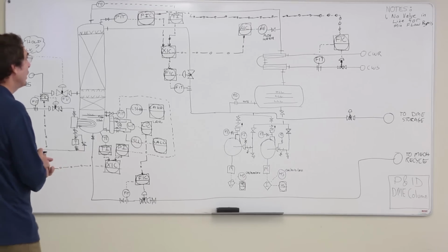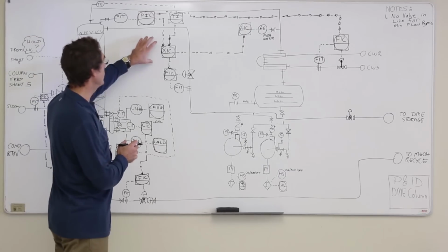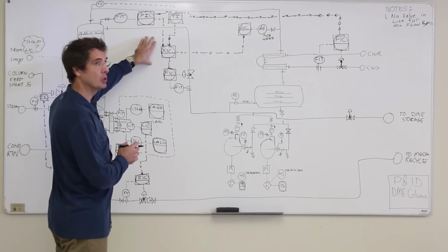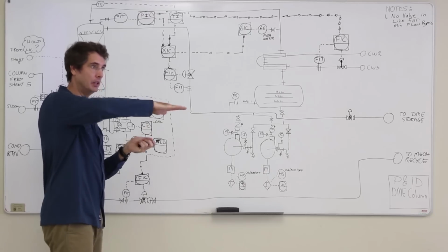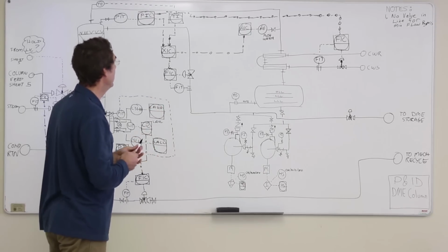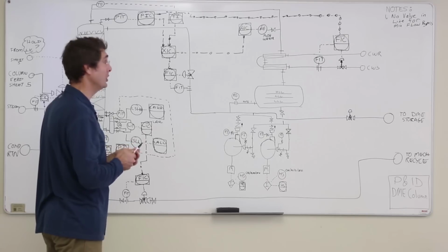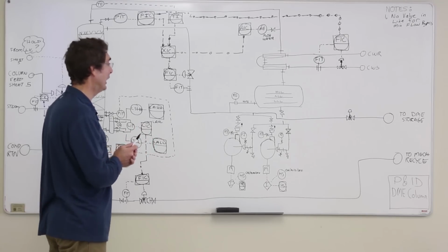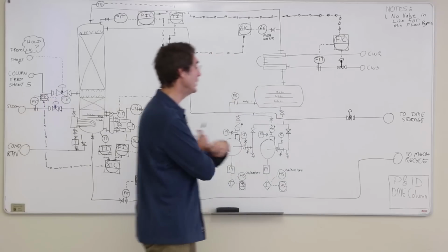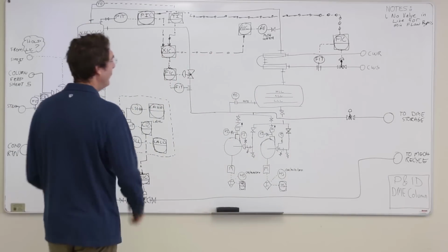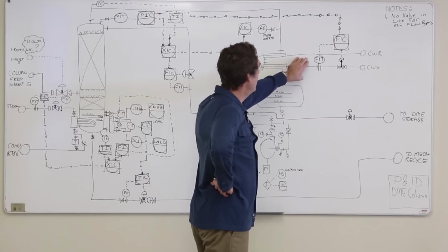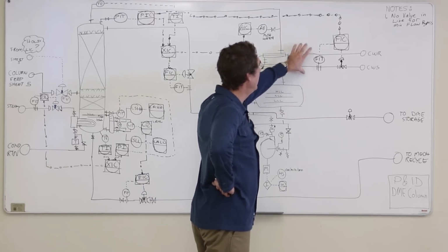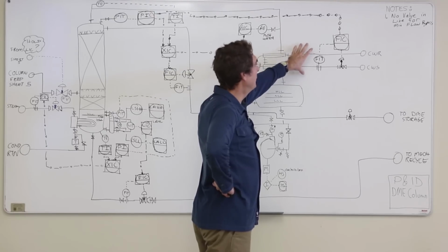Yes, you're not controlling temperature directly, but I think temperature is a very good proxy for what the composition is. Apart from the fact that the curve is really flat, right? The temperature is not changing very much with the kind of compositions that we're trying to achieve down here. The reason why people are saying don't have a lot of flow control on the heat exchanger, I'll cover in more detail on Monday afternoon.